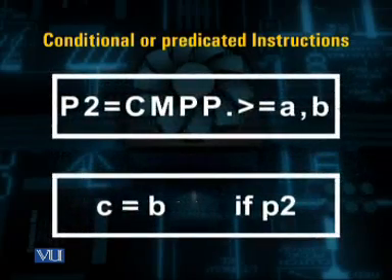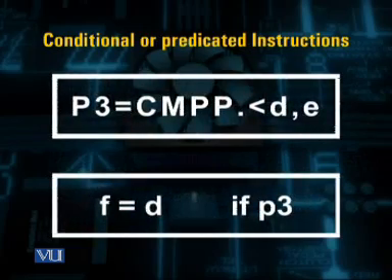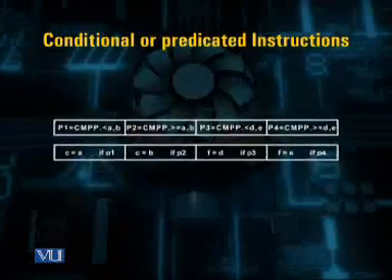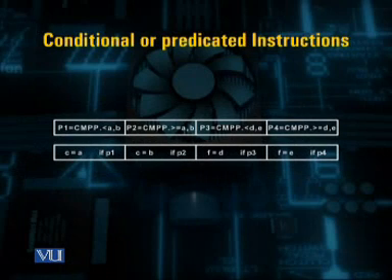Here, the first statement contains 4 instructions, where each of these instructions in the very long instruction word packet evaluates the condition and updates the predicate registers P1, P2, P3 and P4 for 2 different aspects of the condition evaluation.